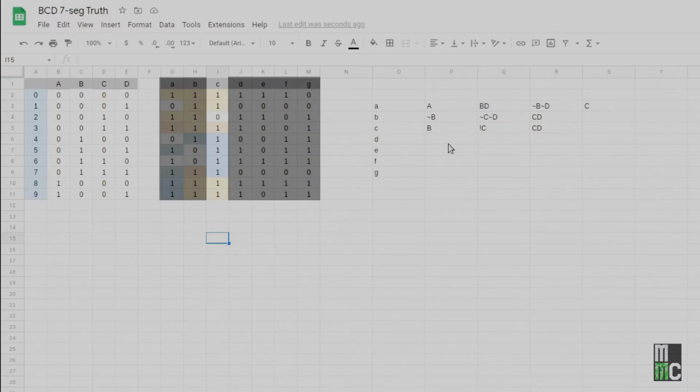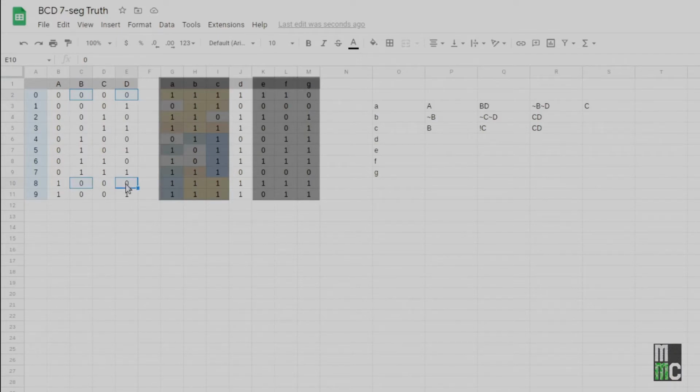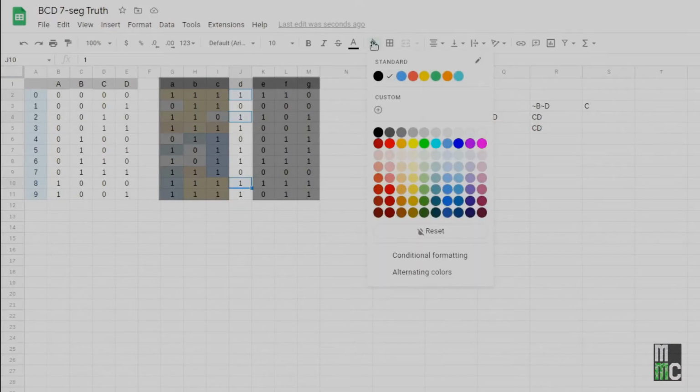That moves on to D. Once again, these 2 are on. When these 2 are on, I can use that if I need to. We're going to look at several other combinations. And we know we've already looked at the not B, not D. There's only 2 of those. So it's a way we can catch a couple there. And we have this one here. And in all cases, you can see that not B, not D is on. So that is a good one that we're going to go with. So I'll do not B and not D. And that gets us this one. Here this one. And then of course this one down here. So that is not B, not D.